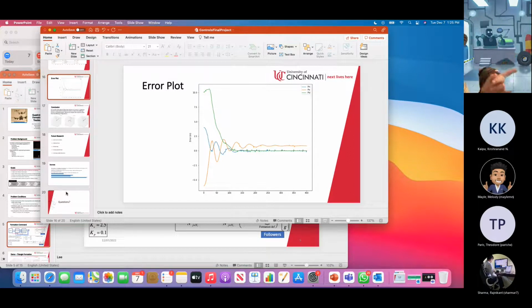Yes. Although we did have to actually go about correcting that while we were fixing it, because we did realize that we don't want to slam through a ship. Yeah, we did have to adjust gains a couple times because it would fall too fast. So is this the error between the quad rotor and the ship location? Yes. Ship location, yeah. So when you talked about you had to do a lot of gain work to make it not slam through the water, is that kind of where your east error came from, or is that still on the boat? Yes, it is. So it's highly exaggerated here, but it would be as if you're landing a foot off or a meter off from where you're supposed to be, and on a big landing pad, that wouldn't be a huge issue.